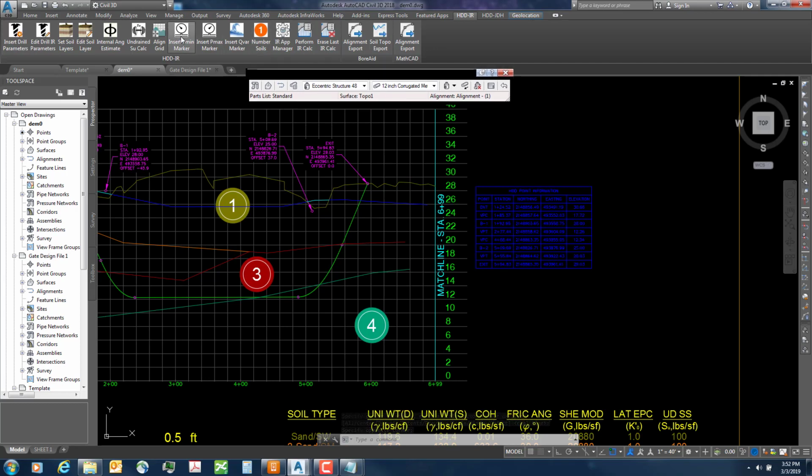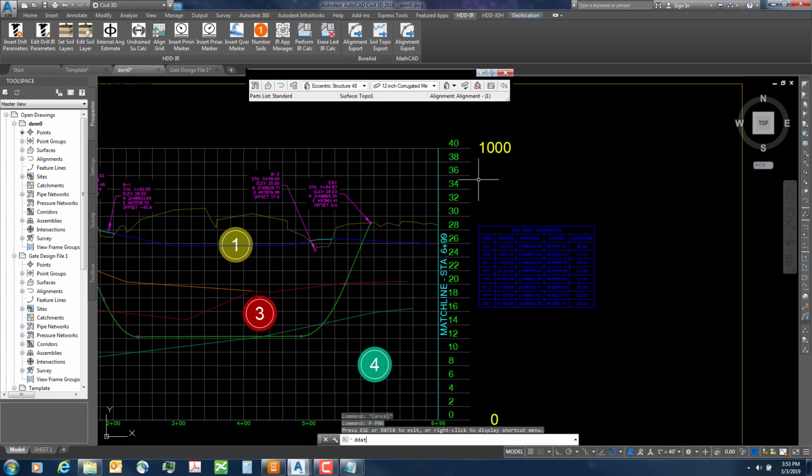So I'm going to insert what's called a minimum marker. I'll set that right here, and the bottom range is going to be a psi of 0, and then I'm going to set a max marker. And we'll set this up at the top. So it comes in at 1,000, but I can change that.